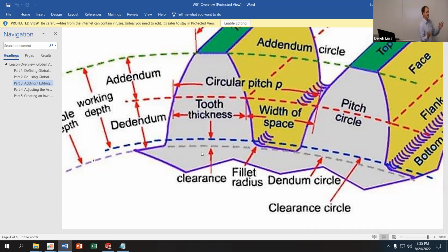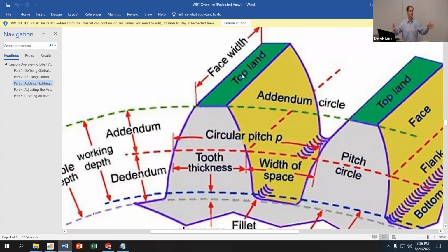If you go back to this old Tony video talking about making gears, you're never going to deposit a gear tooth onto a steel blank. You're going to start with a steel blank that has the size of the top land as the perimeter, and then you're going to cut the tooth into it. Doing it this way is more reminiscent of the actual manufacturing process. Where possible, you want your SolidWorks models to mimic those processes because it helps translate into manufacturing if the things you do in SolidWorks have a one-to-one relation to the actual manufacturing processes.